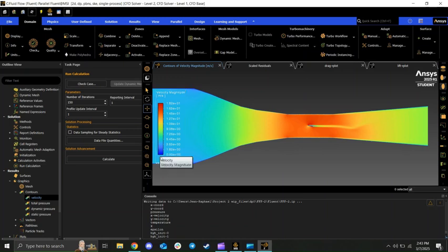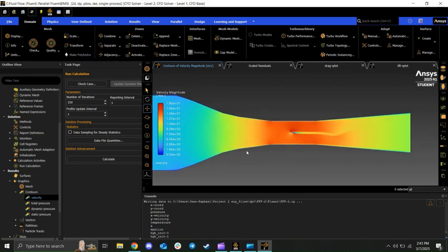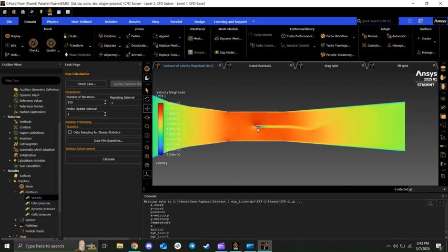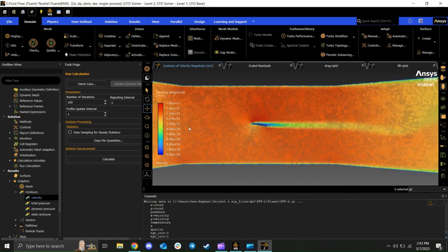And right here, it's the graph. As you can see, velocity is weakest at the entrance of the wind tunnel, speeds up as it progresses through, and then once we get to the test section, zooming in, you can see it spikes, and then once it impacts the blockage, that's when it accelerates around, specifically here on the top corner as it started rotating up. So naturally, it's going to speed up faster here, and then just behind the blockage is when it slows down again, and you can see the wake of the wind behind it.